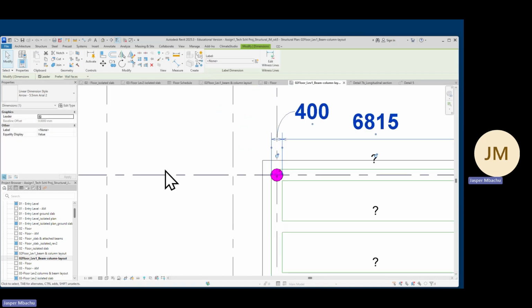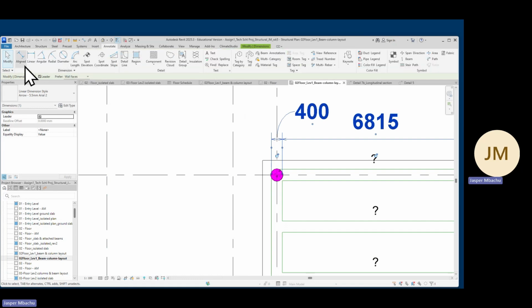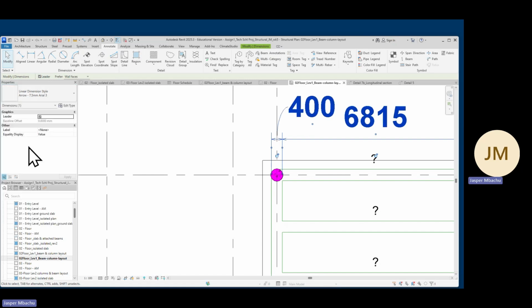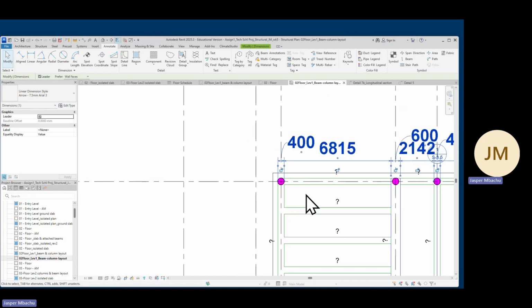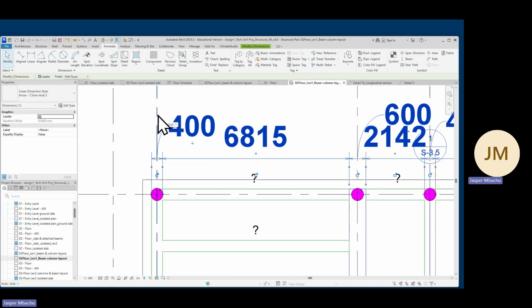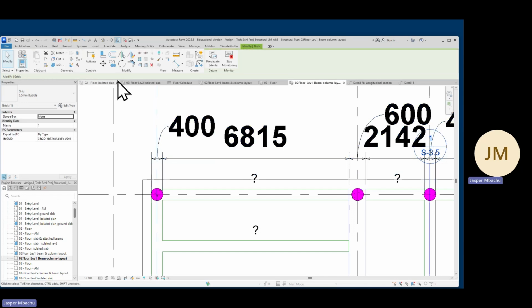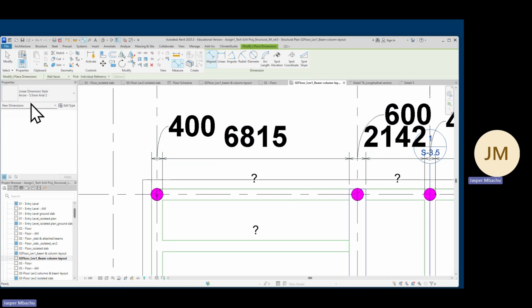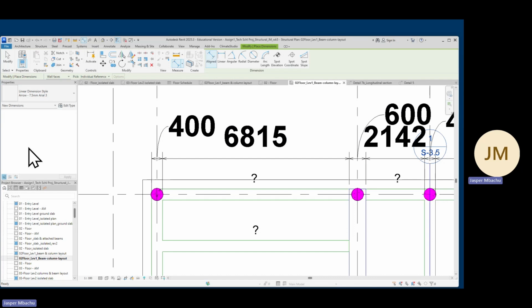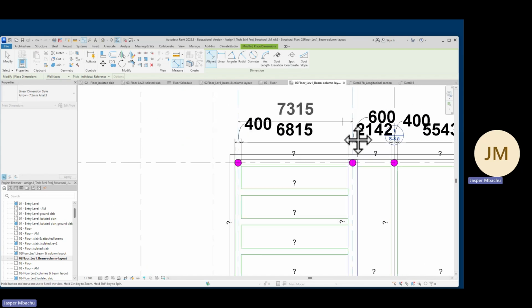Okay, when that happens, then you take another annotate, and this time around, use a bigger font size, maybe 7 or 7.5. If you don't have it, just use edit and duplicate and give it 7 point. That will be for center lines, so only annotate center lines. Just pick only the center lines of the grid lines. Click the grid lines only.